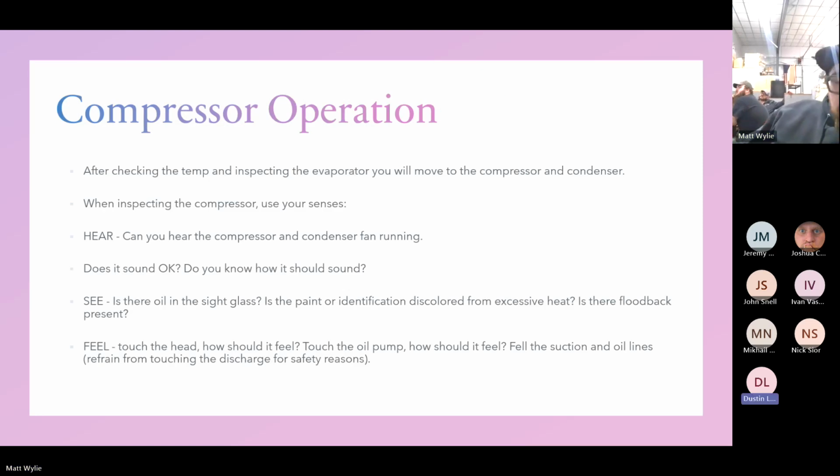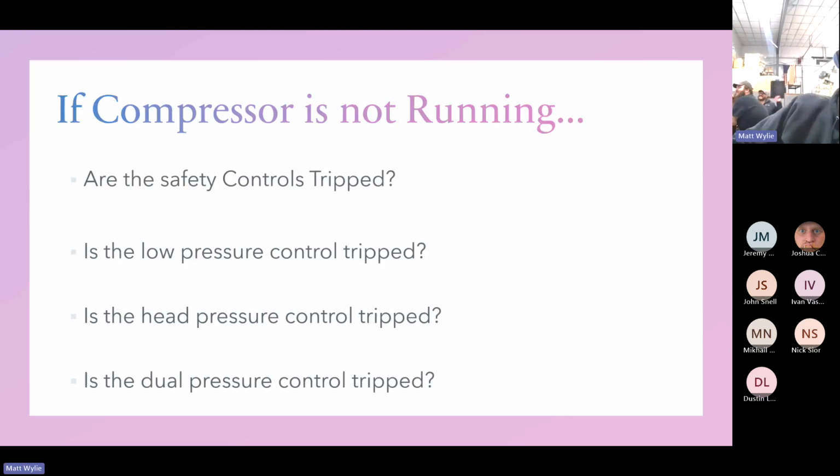How do you know if your pressure switch is open or closed? Check your power. Check continuity across it, or check for voltage drop across it. So what should the voltage be if it's closed? 0 across it, or 120, or whatever it is, on each side.